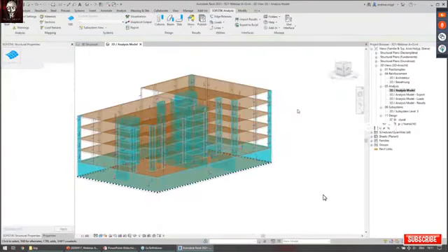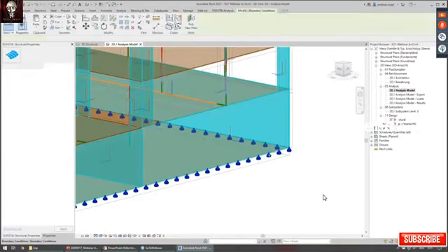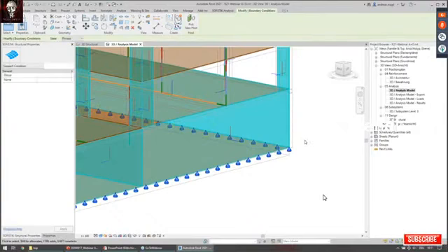Same for areas, or what is new for version 2021, you can also assign groups and a name to boundary conditions. So, for example, especially important is the fact that you can assign groups. This allows you to activate and deactivate a boundary condition during, for example, a staged analysis in SOFiSTiK later on. So, for example, to apply temporary supports in a staged analysis.